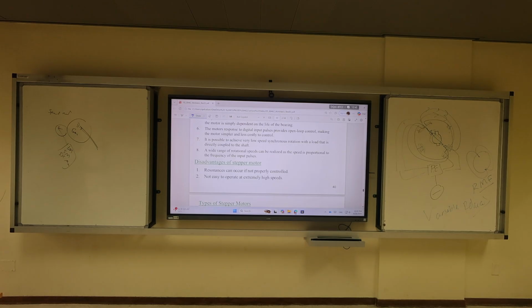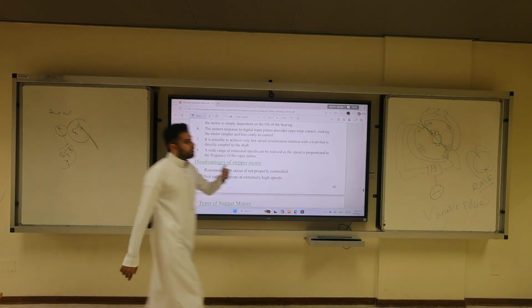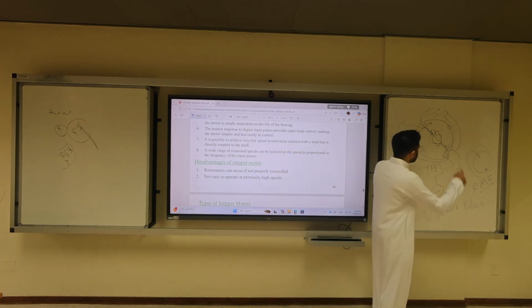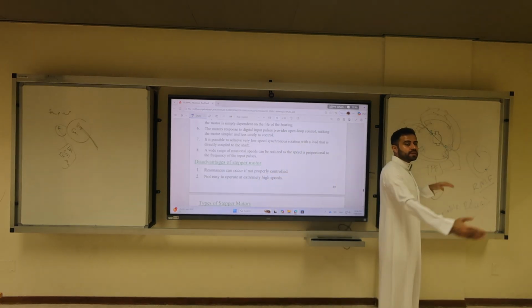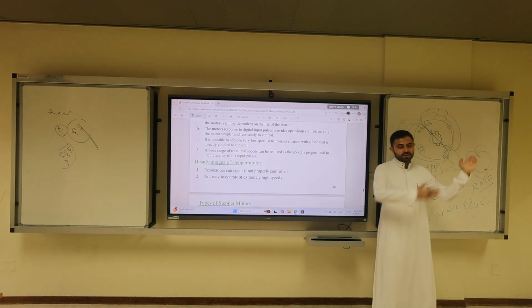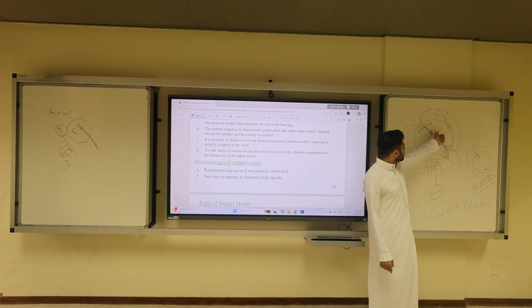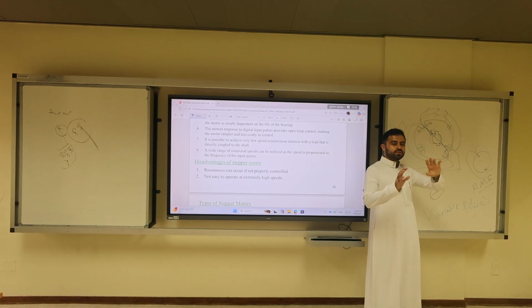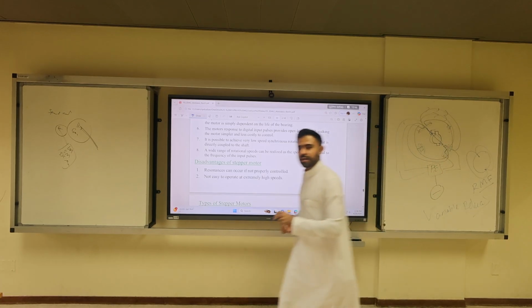But from 1 p.m. to 1:05 p.m. the sun is going a little bit down, so that movement is very slow. You don't see it by eyes. But if you're talking about maintenance, they want to make the solar panels flat, the stow position we call it. Maybe you can send one central command and have it go 90 degrees by having the correct pulses, skipping all the other pulses. So you can make it a very fast movement. From here to 90 degrees, you just energize. I'll explain it and then you will get an idea how to do it for solar.